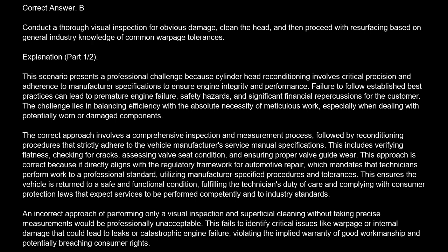Failure to follow established best practices can lead to premature engine failure, safety hazards, and significant financial repercussions for the customer. The challenge lies in balancing efficiency with the absolute necessity of meticulous work, especially when dealing with potentially worn or damaged components. The correct approach involves a comprehensive inspection and measurement process, followed by reconditioning procedures that strictly adhere to the vehicle manufacturer's service manual specifications. This includes verifying flatness, checking for cracks, assessing valve seat condition, and ensuring proper valve guide wear.